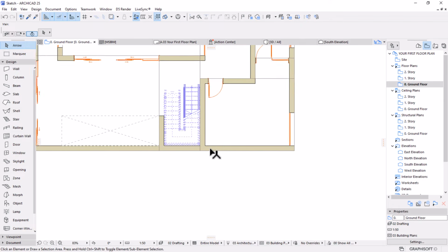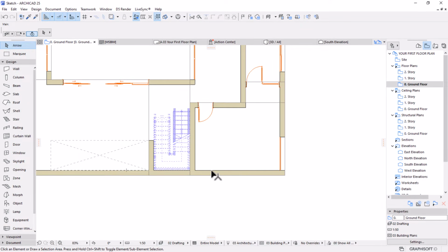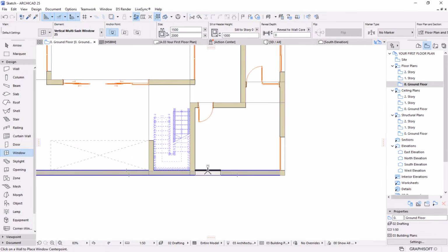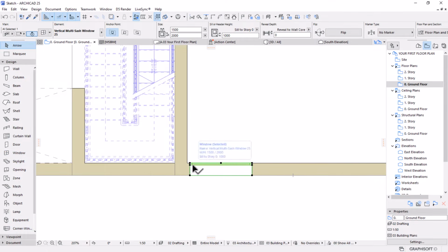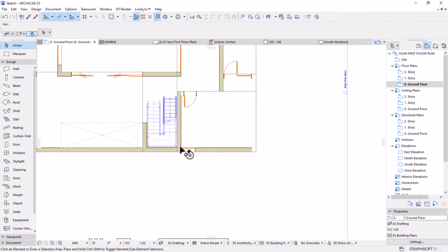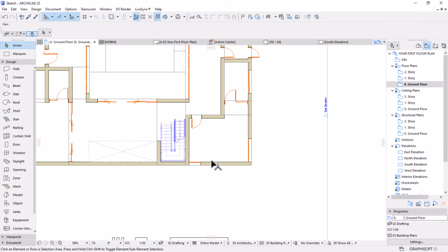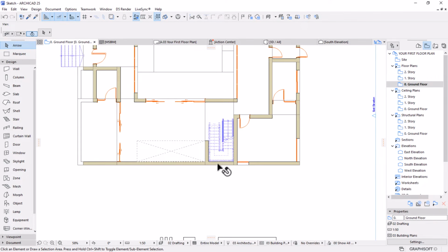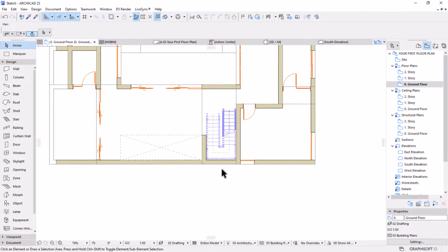So from here we have another one for cross ventilation effect. W on your keyboard, then place it inside and outside. Click Control D to drag it to the corner right there. This I'm going to change to be 1 meter. Okay, Control D and position it right there. Perfect. So we have this, and then we are left with one.